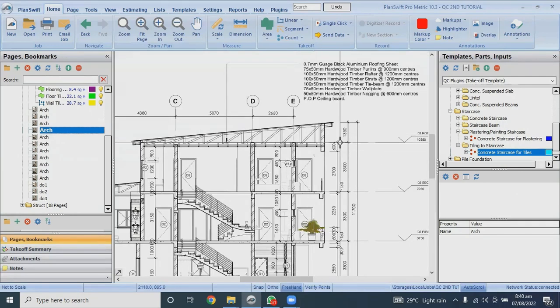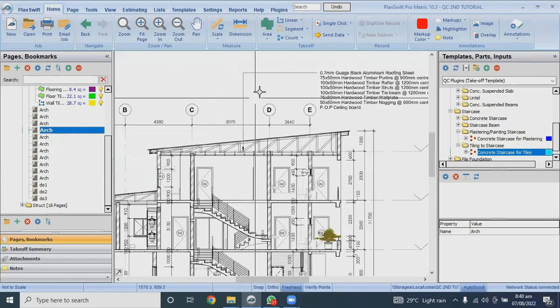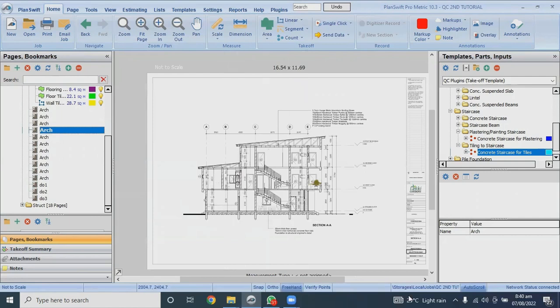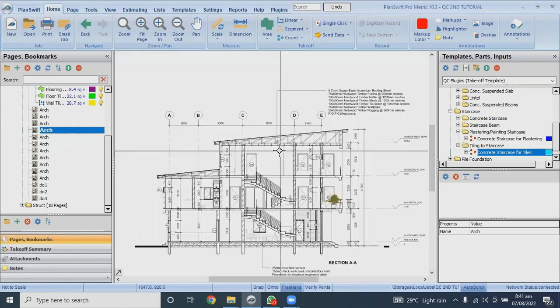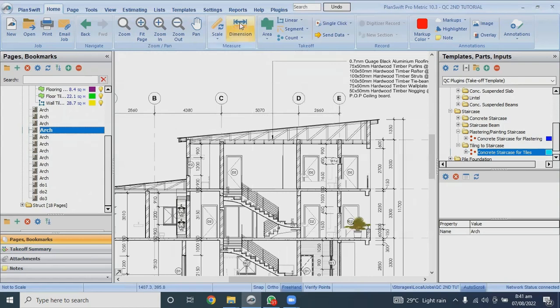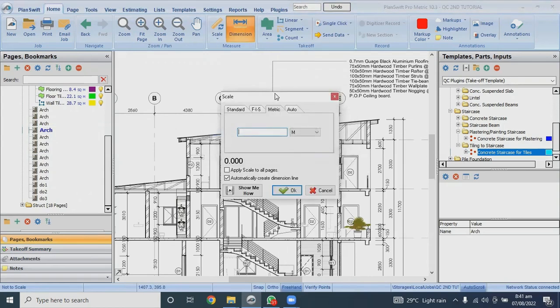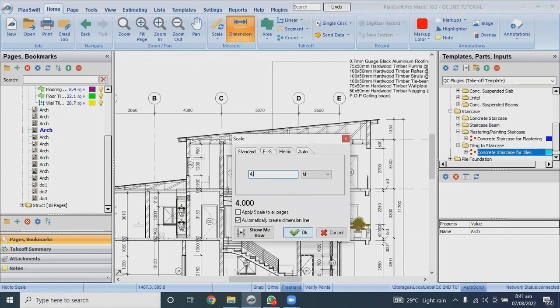So on the second floor, what do we need? We need the length of a rafter. If you are taking off, according to this drawing you have to group your roof measurement into two: one is this one and the other is this one. Whenever you want to take off for this roof, you can name this one roof A and this one roof B. Let me consider roof A. Let me scale: 4.38. Click OK.